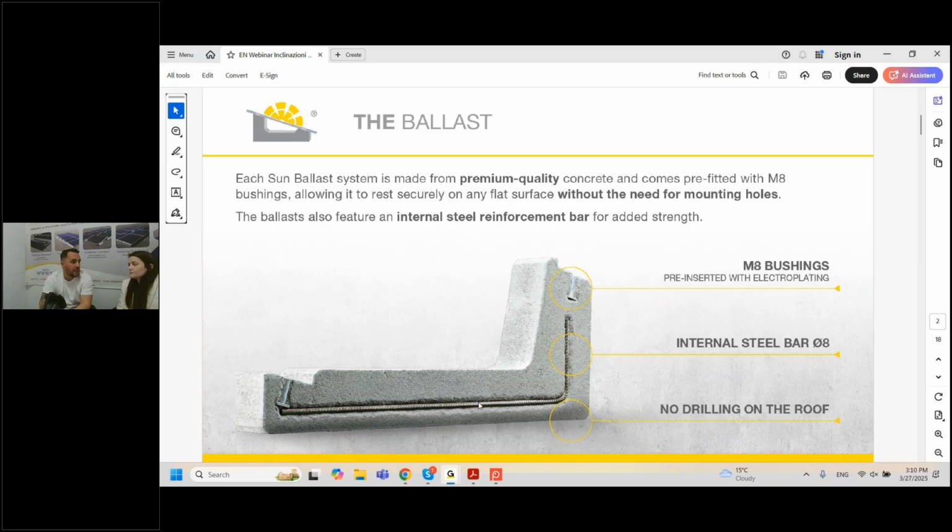It only takes the installation manual once, or you could get our technical report. If you're an installer on the roof, you can direct your guys on how to install it. There's no need to buy hardware outside. Everything comes with the ballast offer, and there's no need to go and purchase anything. You don't need to buy CMU blocks, because the weight is also the ballast. You don't need to buy profiles or any other type of accessory to make the system more resistant. So pretty much as you said, just the ballast, the clamp, the rubber mat that we put under, and you're good to go.